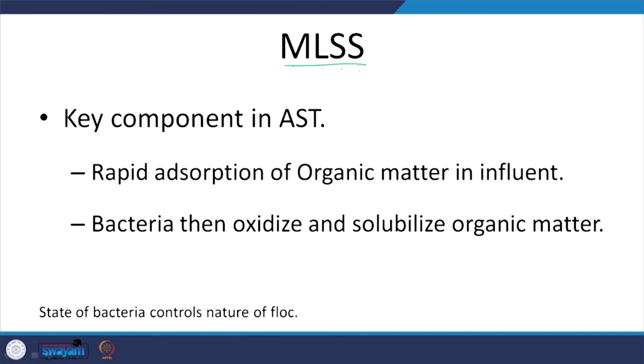So, what is this about? You know that waste is coming in, and here we have our aeration tank and then our secondary clarifier. A considerable fraction of the sludge is going to be returned, and some of it is wasted, and then we have the treated effluent water. And what do we have here? We know that the concentration of microbes here is going to be pretty high. So, the contents of this aeration tank are called mixed liquor suspended solids.